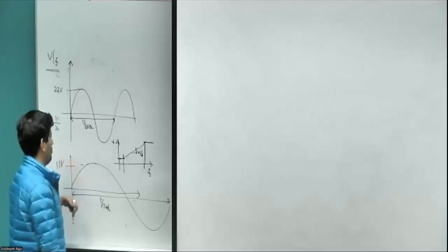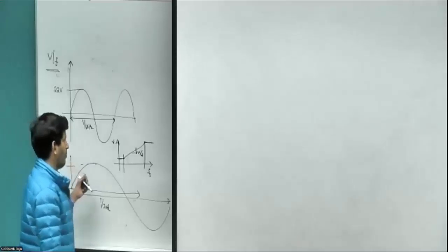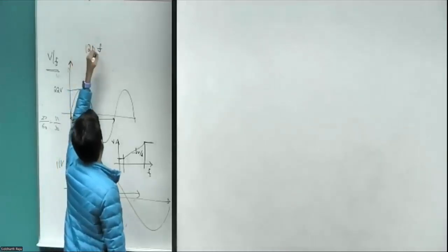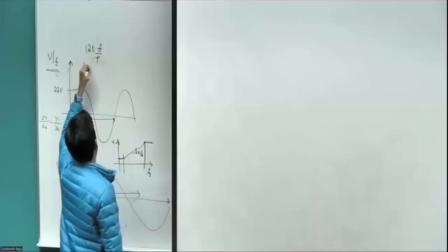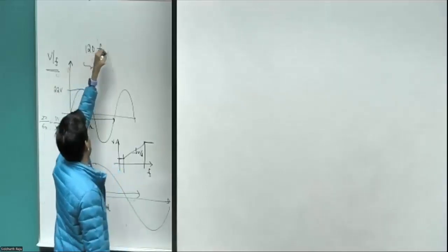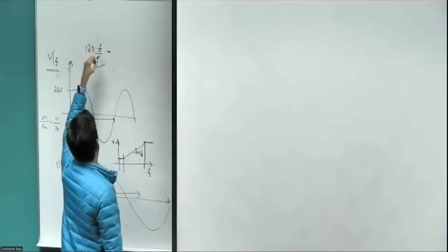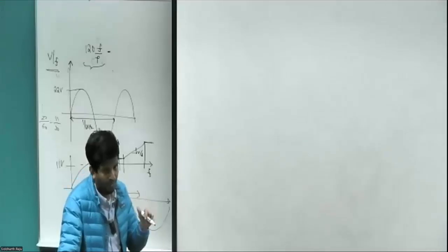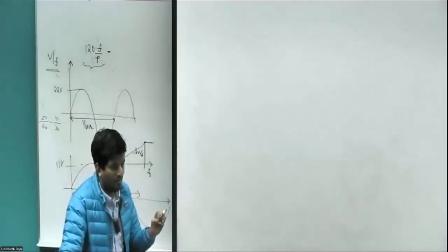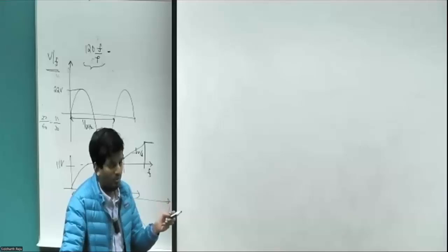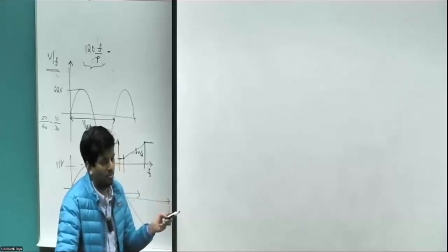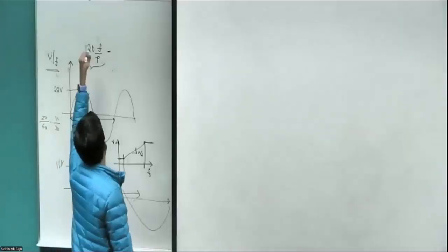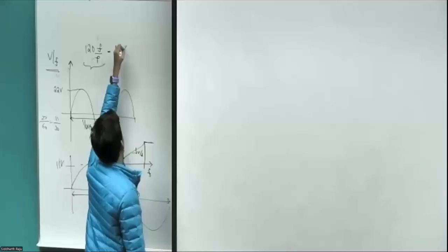In the induction motor, you can guess what the speed of the motor would be, very close to the value of what it will be under no load using this formula. It's a very simple derivation which we'll do later. But what it says is, given the frequency and the number of poles in the motor, the motor that we have on the table is a 4-pole motor. Typically induction motors, if you were asked to take a guess, would either be a 4-pole or a 6-pole induction motor. It's very hard to find a 2-pole or 8-pole induction motor, at least for commercial applications.